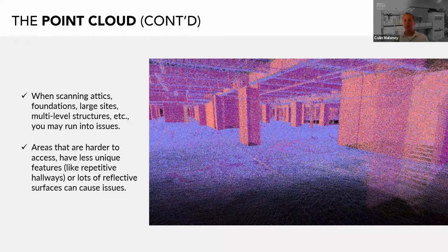Processing requires all areas have data connecting one area to the other, so they can properly be glued together. You've got to think of it as kind of like the data has been logged and now they have to glue the point cloud together. Mirrors, moving objects, people following you, big trucks can also trick the process and therefore give you bad output.